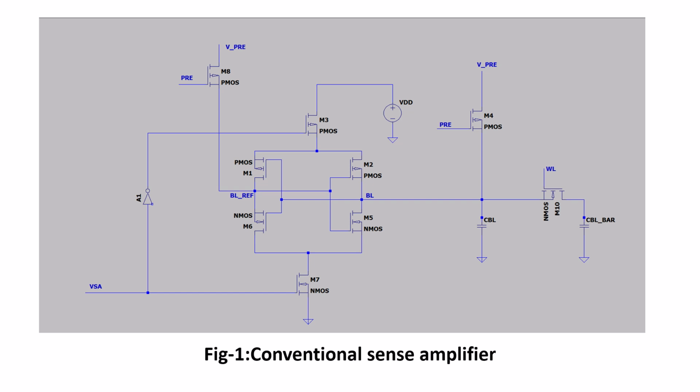across this bitline voltage. So this bitline voltage is pulled up to the VDD and this bitline ref is pulled to the ground, which is essentially again given back to the CBL, and still this word line is turned on such that this VDD voltage is again written right back to the CS storage node capacitance and it restores its value.